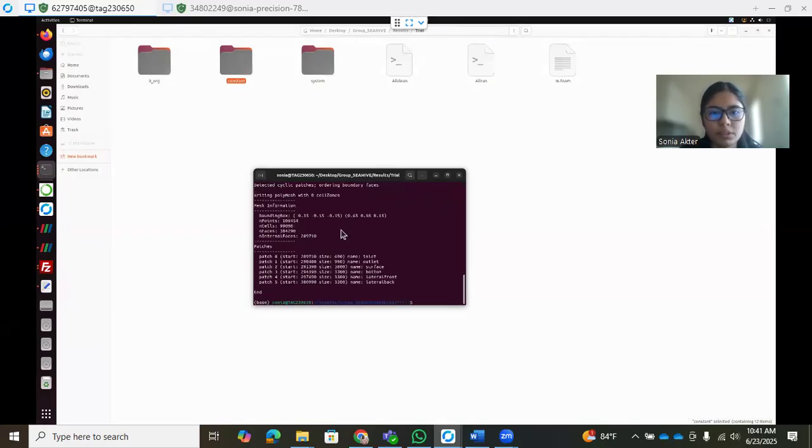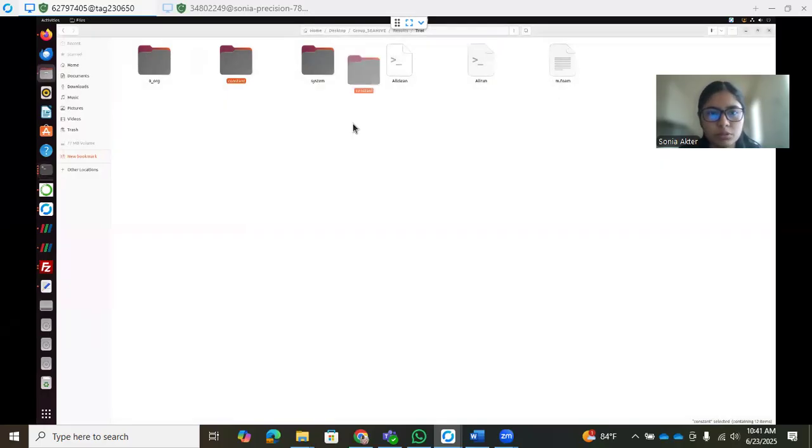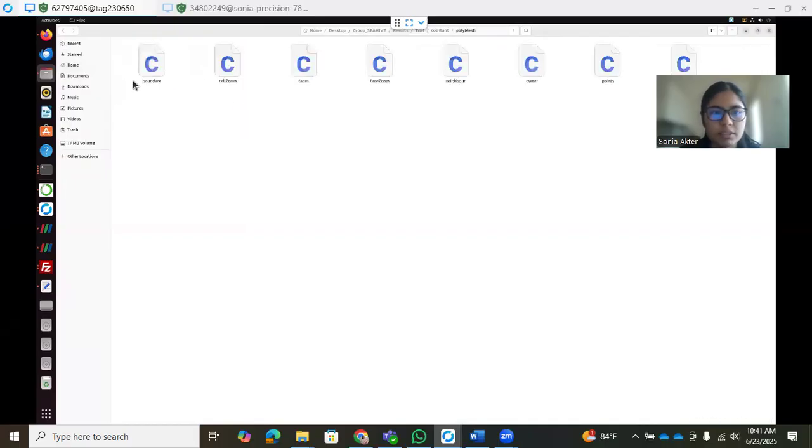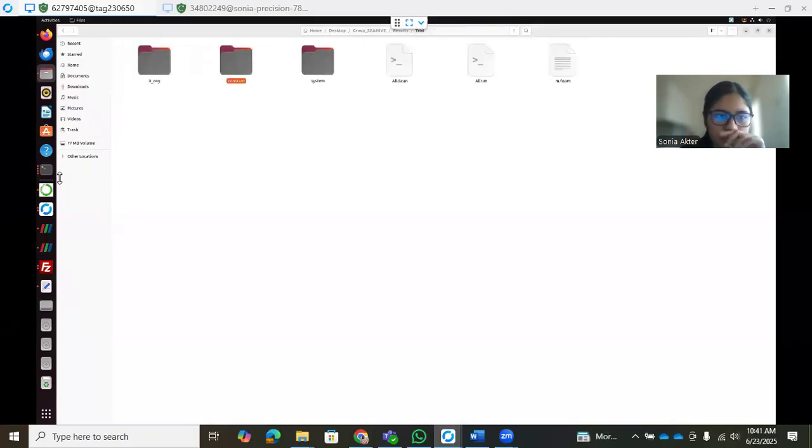If you see that the mesh is already created, and if we go to our constant folder, it also created another folder named polyMesh, where you can see how many boundaries and other information like how many points and cell faces are generated after running the blockMesh command.